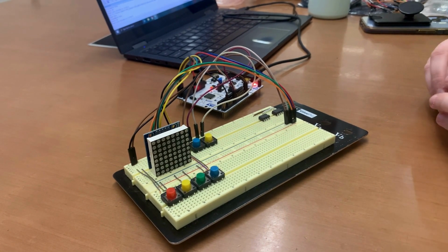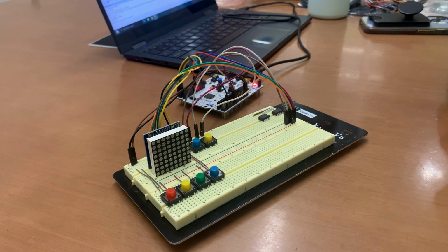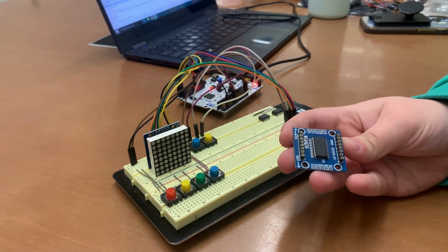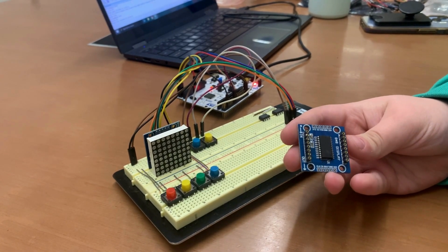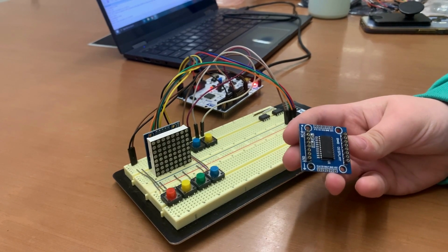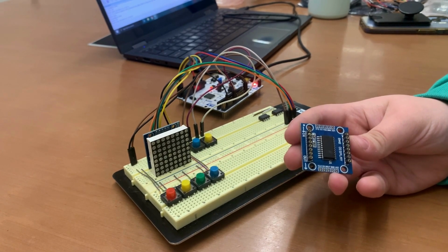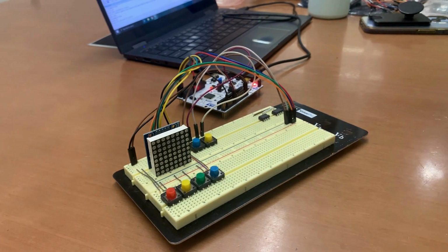Through this, the microcontroller is able to control a large amount of LEDs, that being 64 in this instance, using only 3 GPIO pins. This is done because the LED is connected to a MAX7219 driver. The driver is able to take in an address, that being the column or row on which the microcontroller is displaying, and it outputs the specified LEDs to be turned on and off. With that, we can get into the function of the game.